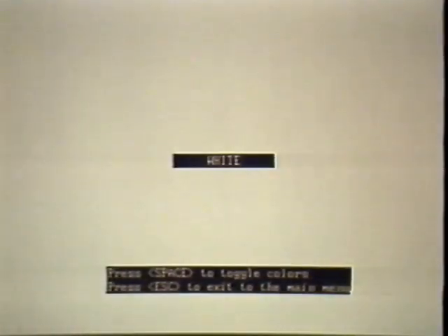This means that the color on the screen would appear to change as the intensity changed. The screen might fade down to pink rather than gray as the brightness or contrast was reduced. To adjust cutoff, you will need to obtain a full white screen or a thin white line in the center of the screen. Then set brightness and contrast to mid-range.